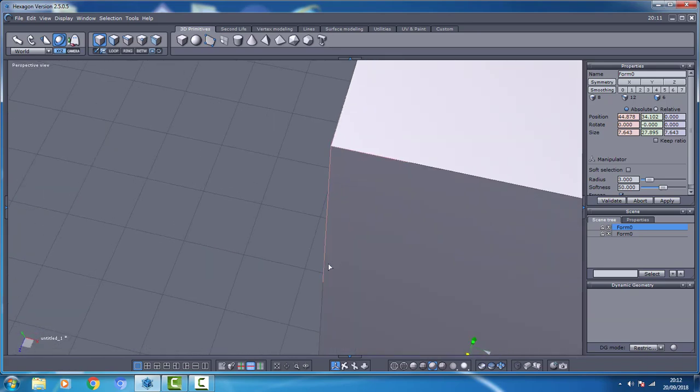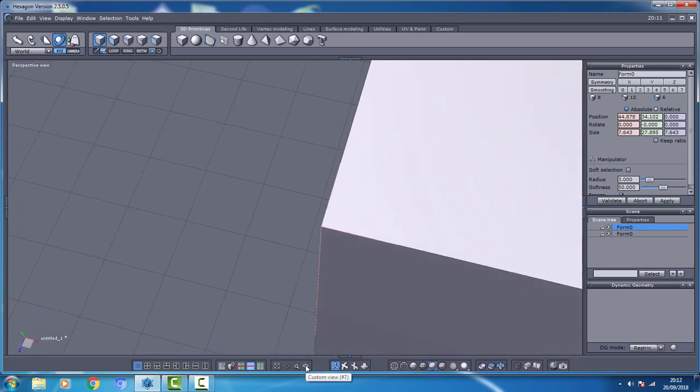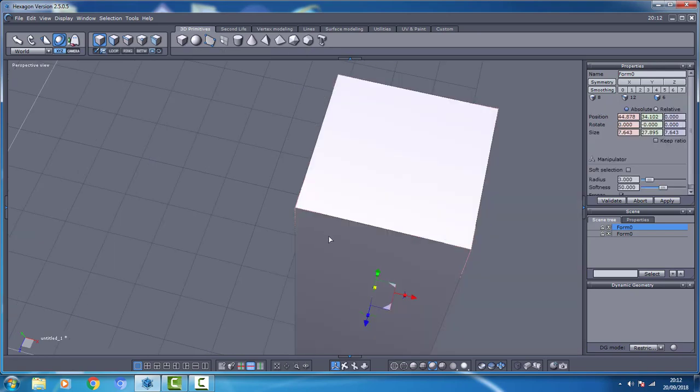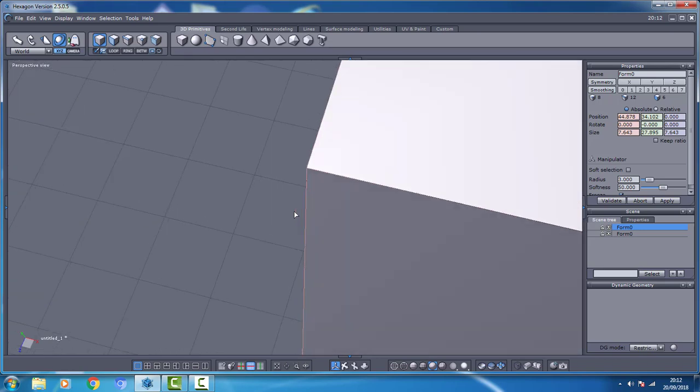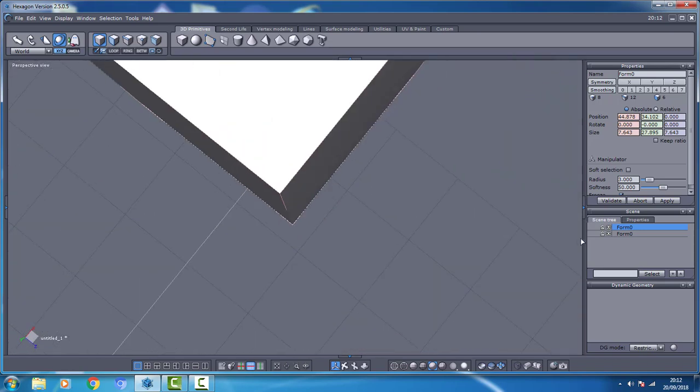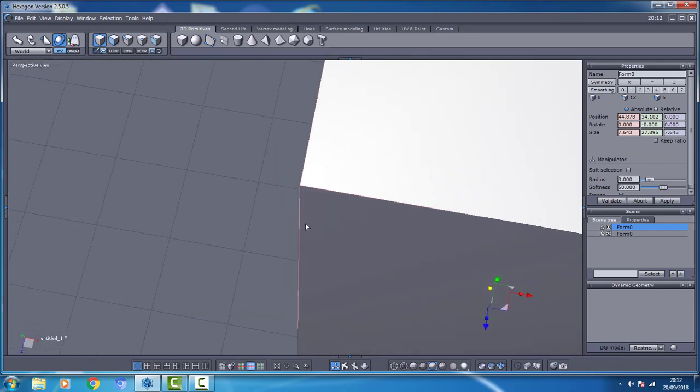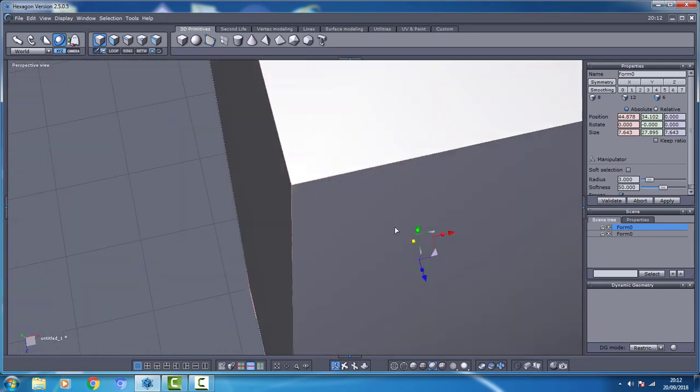And this is where it brings me to this last little tiny button. What it will do is set the pivot point for the camera that we're looking through to rotate around that particular area. And this is something that you're going to be using a lot. So if we click on that, you get this little crosshair there, and you can just click like that. And now when we zoom in, it's zooming straight on the area. When we rotate, it's rotating around that particular area.